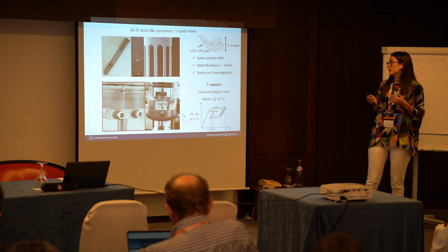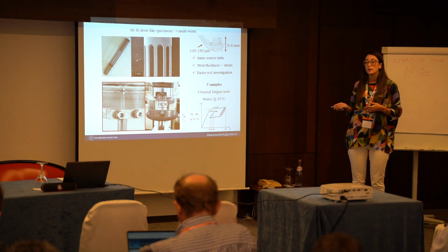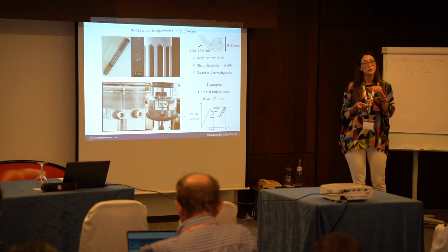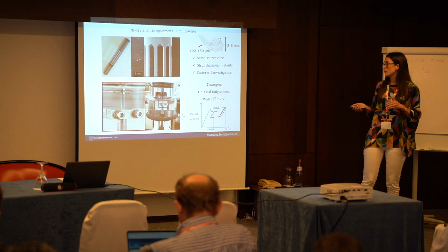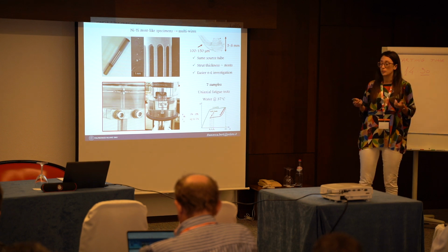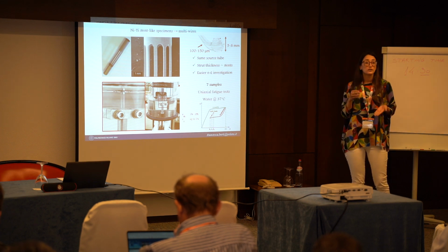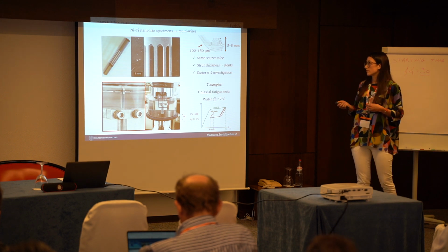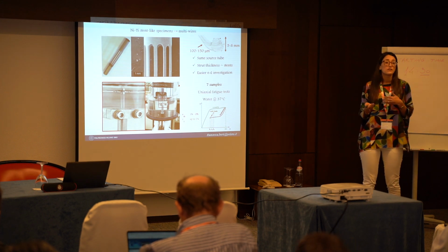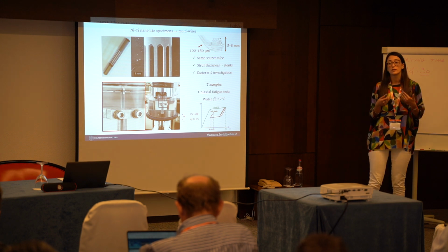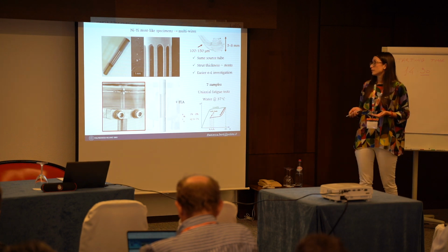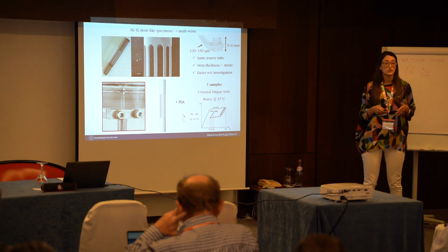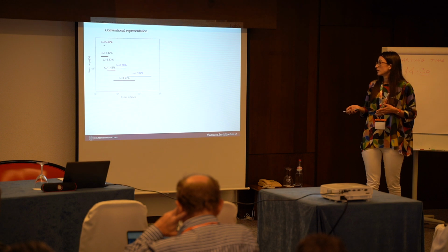I performed fatigue tests on these samples, mimicking body temperature at 37 degrees, and all these samples were tested in order to mimic the stent life story. So they were preloaded to mimic the crimping, partially unloaded, and then the effective fatigue cycle, investigating different combinations of mean and amplitude strain, was performed. I also performed finite element analysis in order to have more detail on the local stress and strain path.